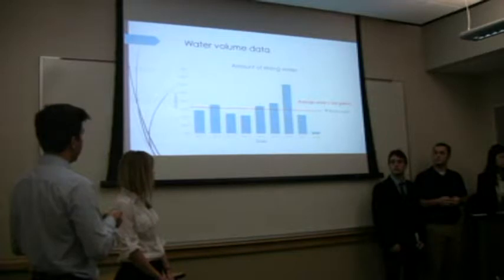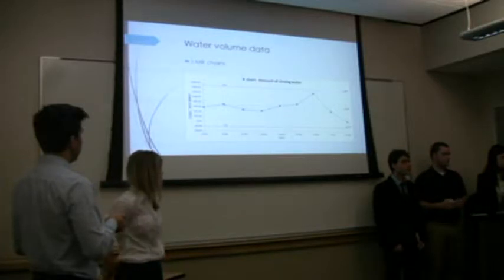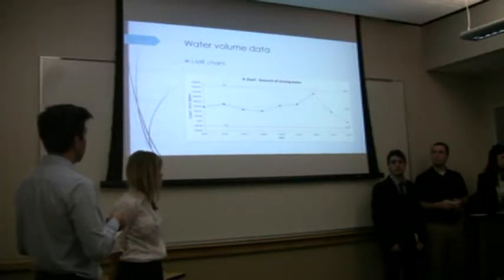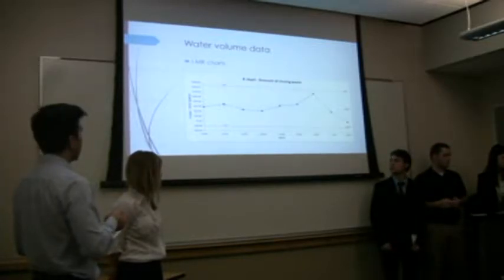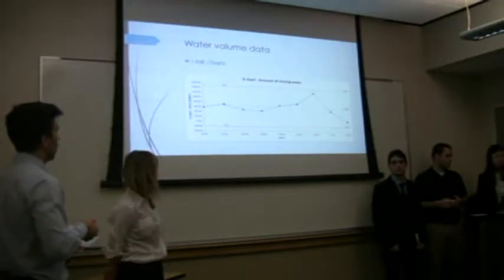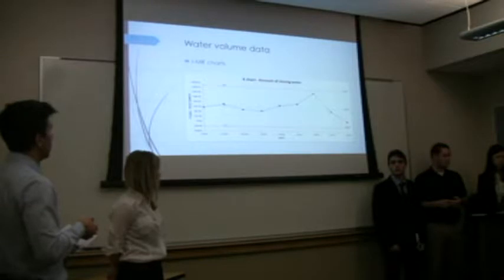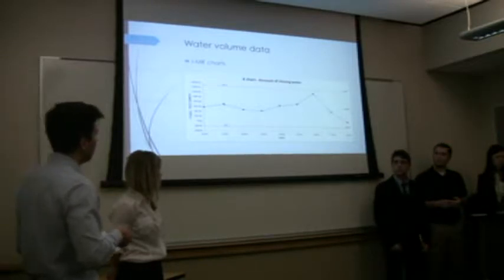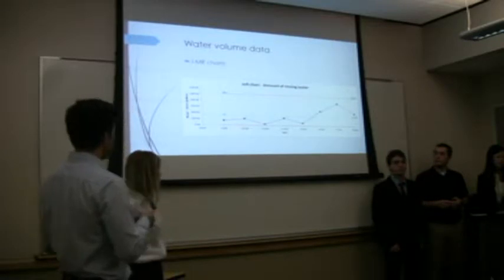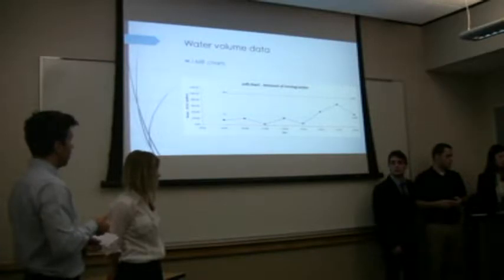And we also wanted to use a control chart to see the variability and also the moving range of our data. These are the upper control limits. If there's any point outside of those limits, that means the process is out of control, or if it's lower than that. So it shows that it's in control, but there are some changes here on the same days. This is the moving range, and also you can see that the process is in control, but there's some variation here.